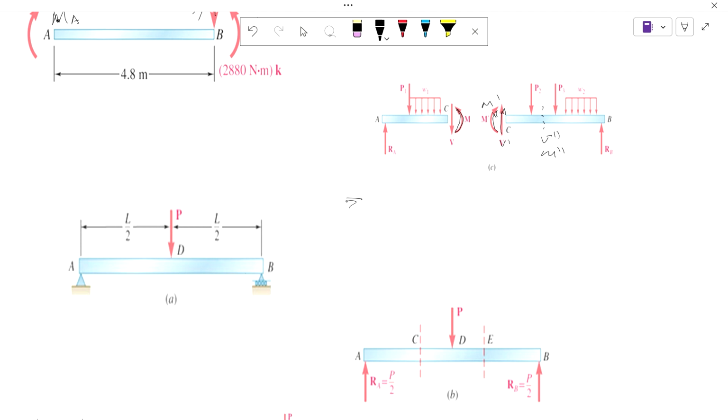So if you have summation of forces at x equals 0, AX equals 0, and that is because this is a fixed point, and this is a roller, so we have By. So summation of forces at y equals AY plus BY minus P is equal to 0, right?